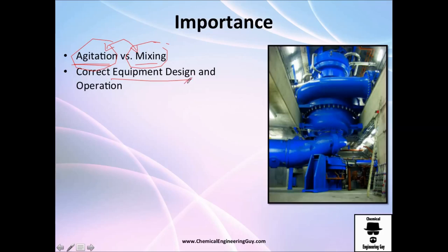I mean, when you're doing the numbers, if you have one task to do, you have fluid in A and you want to move it to point B, you want to design it. And once it's designed, for example, you already have a pump, how can you change piping and so on to operate that? Is it better to operate the pump at 3,500 revolutions per minute, or is it better to check and change the impeller size? And what's the better or the best operation point?